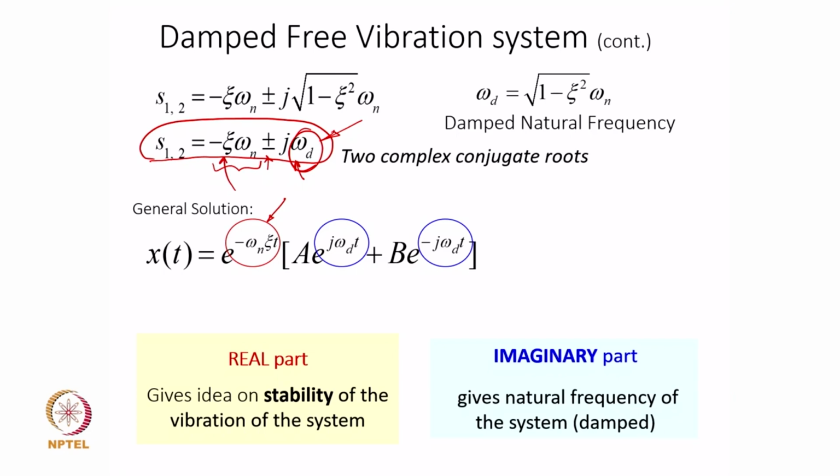Natural frequency of vibration is important for avoidance of resonance, but as you are now noticing, a complete understanding of the roots of the vibratory system will also give you added information on the stability of the system.